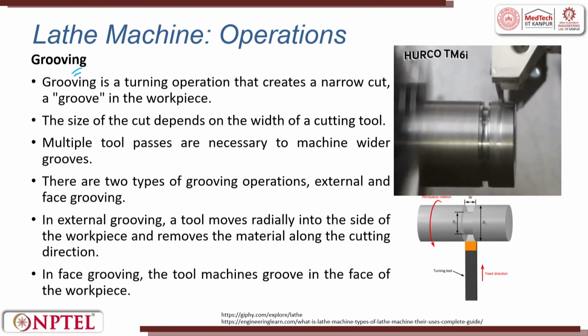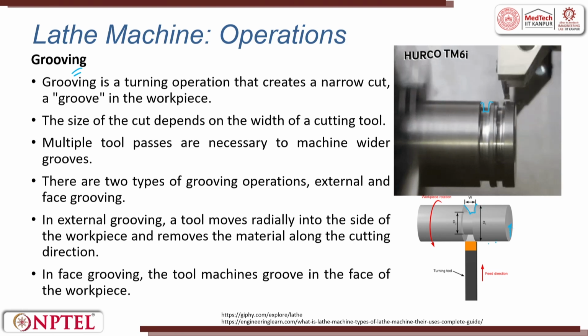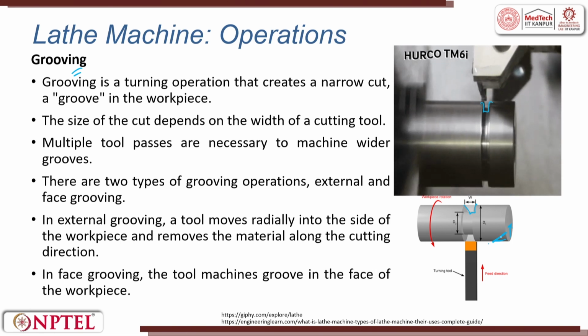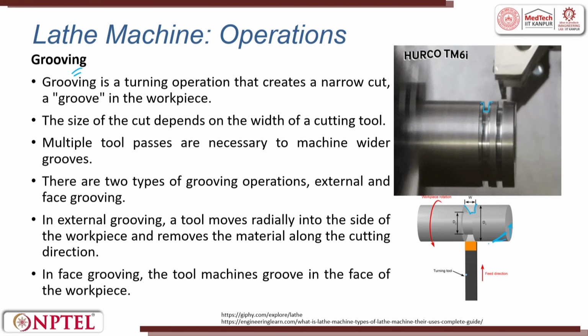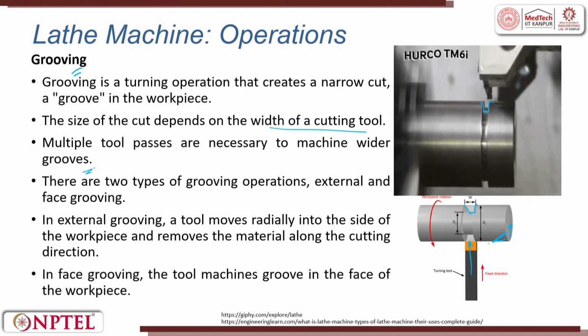Grooving. Grooving is something which is done in between. Facing was this, turning was reducing the diameter, taper turning was bringing the angle. Now grooving is moving offset from that distance and then moving only perpendicular to a certain depth such that a groove is created. The size of the cut depends on the width of the cutting tool. Multiple tool passes are necessary to create a groove.